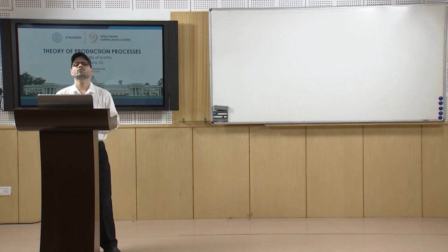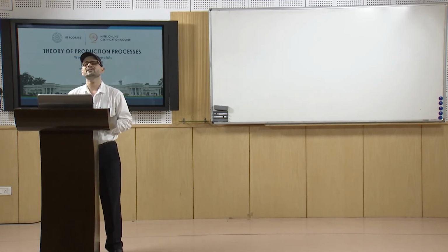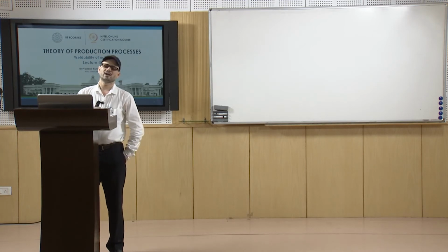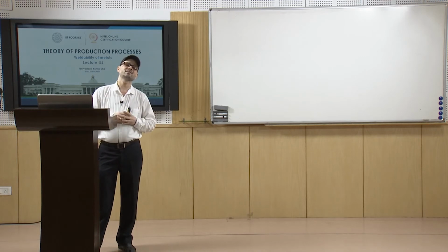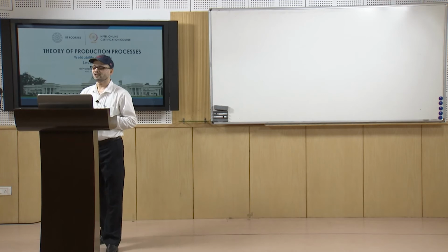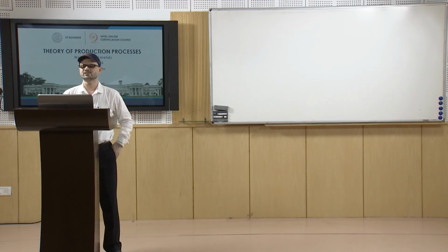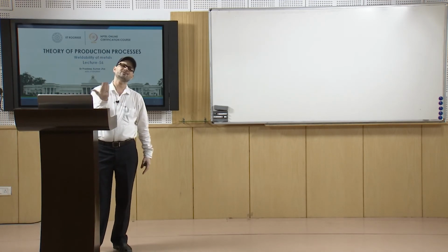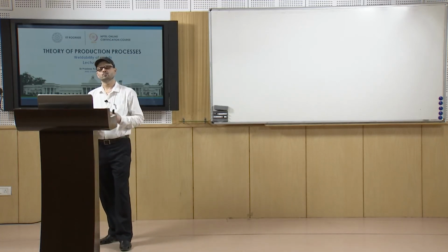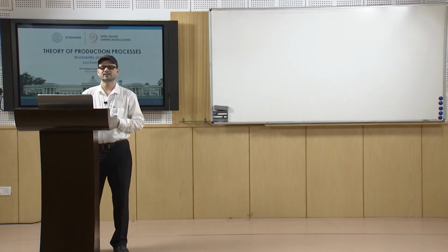Alloying elements also provide grain refinement. Many a times the alloying elements are used for grain refinement, and normally you have elements like aluminum, vanadium, titanium, zirconium and nitrogen acting as the grain refiners. In such cases they act as heterogeneous nucleating agents and make fine grains. So, they act as grain refiners in the low alloy steels. Once you have refined grain, you can assure a fine grain structure that will provide better mechanical properties.